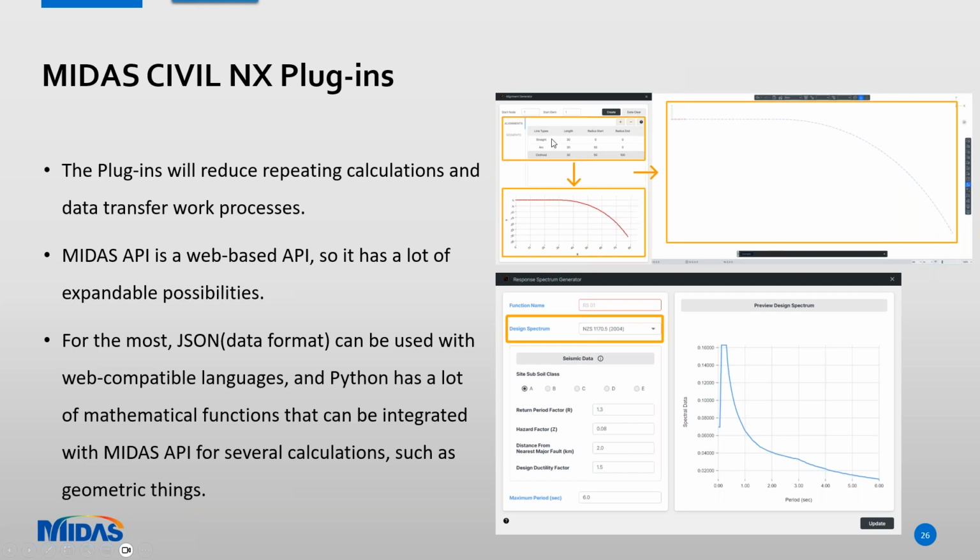Parabolic. So the user can specify, let's say, the total alignment length, and then we can specify the number of segments in it. So there is a first alignment here, a second alignment here, then a third alignment is something else. So we can mention that. Before we actually generate that, you can cross-check it using this particular guide diagram. That is the main idea, because this is not available in the wizards which are available, right? So that's why we can first judge whether the geometry generated is as per our requirement or not.